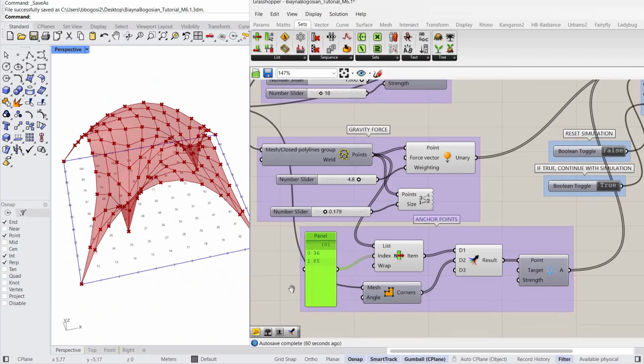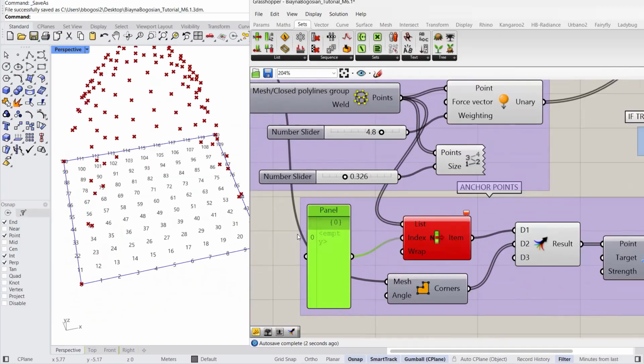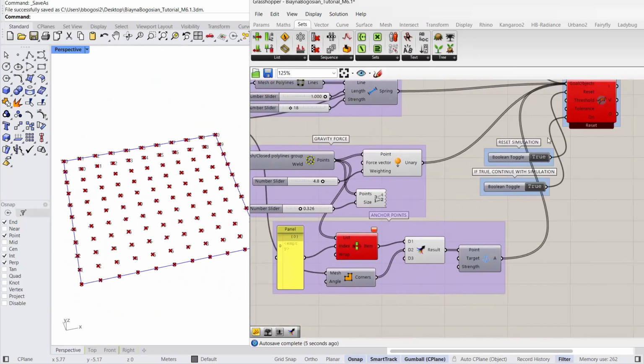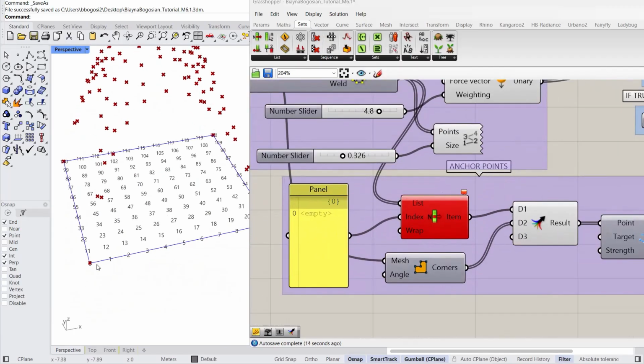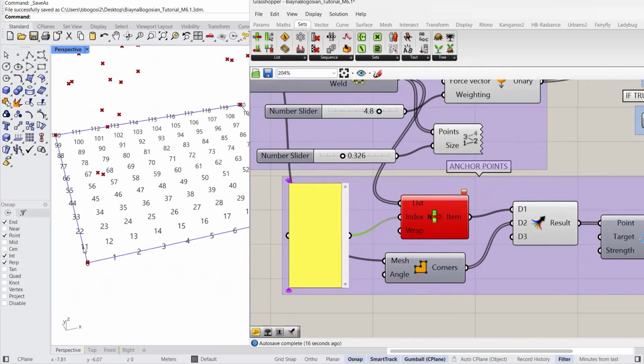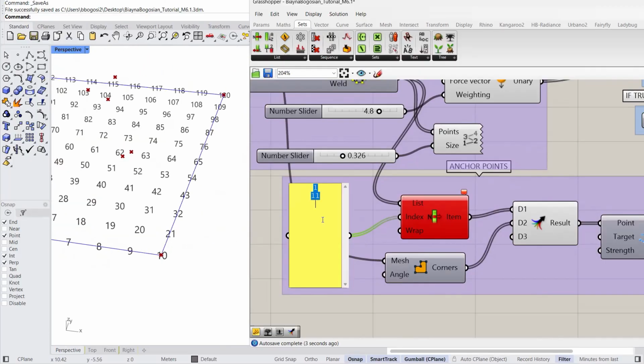So just follow this along. I'm going to go back to my indices, and we can just all use the same number. I just need to be aware that it will require resetting. You can see that when it's red, it requires resetting. It's red because right now it's empty, so don't worry about it. We can fix this. The numbers that I want to extract, let's say 3 points, but I'm already extracting the corner. So go ahead and enter 1, next line, 11. Next line, let's do 9 and 21. So enter 9, next one, 21.